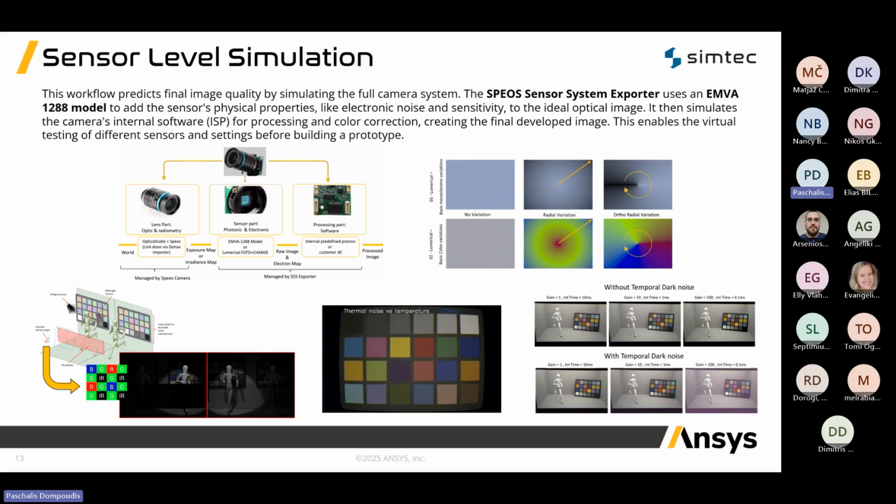For even higher fidelity, we can use Ansys Lumerical to also calculate the spatially and angle-dependent quantum efficiency of the sensor. Second, the Sensor System Exporter also simulates the camera's internal image signal processor. This applies algorithms for demosaicing and color correction to create the final developed image.